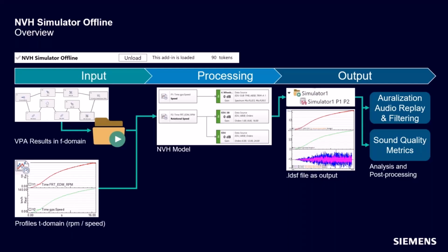Those are the inputs to this simulator. And so I'm not dynamically driving it. There's no vehicle model involved, but this is really just the first step to say, okay, I've got this VPA. I do that road noise, virtual prototype assembly assessment that we just looked at. And now I want to say, okay, what does that really sound like? I see that 380 Hertz peak, but what does that sound like? And do I really care? I'd like to hear all three of those vehicles maybe.